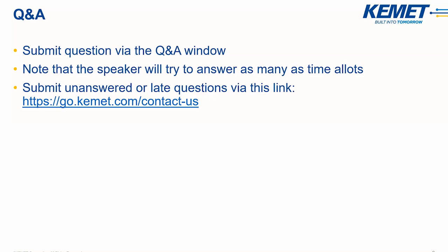Yes, so when you wind the capacitor, basically you already have the capacitance. The capacitance is there. But the problem is you have to connect the capacitance to the rest of the world to make it usable, right? So we apply this spray material, which is a conductive material, in order to create, let's say, the termination.